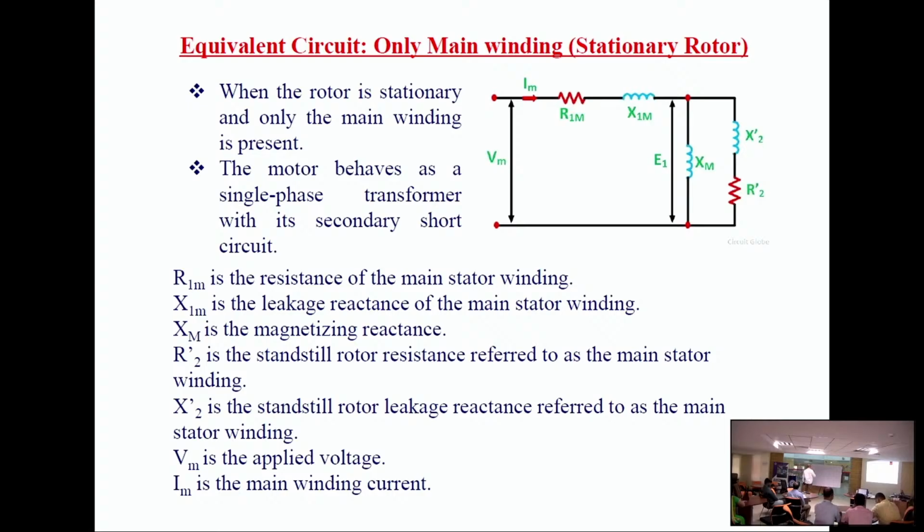What about the running condition? Will you get the same induced EMF or different? It will reduce. So E2 will change to S E2.